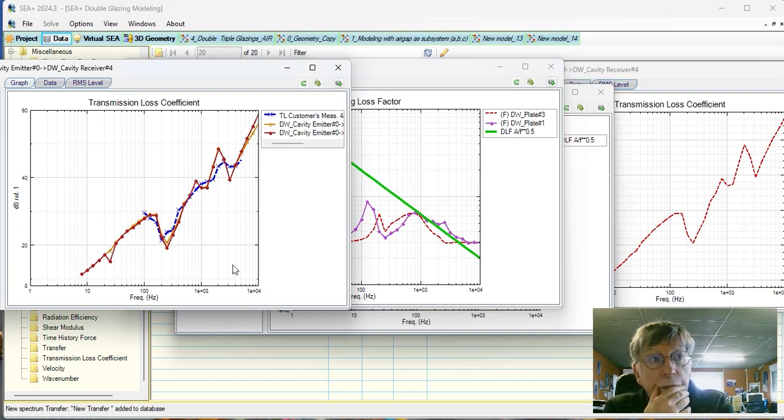You see that you don't have to really puzzle about modeling double glazing. It works. Residual error are mainly due to damping, exact damping, or junction modeling. We don't know exactly, but we can have a very good approach of it, especially if you look at my presentation.